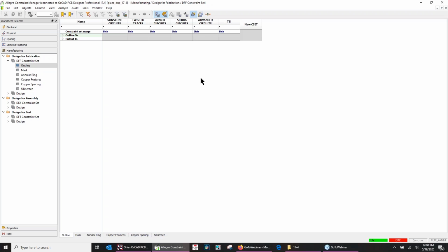What we want to do is say, why do that as a post-process? Definitely why do that after you've sent it to the board house and you're waiting to hear back from them. When you really think they're building your board, they're doing checks on it just to put it on hold and send it back to you to tell you there's problems. And trust me, if they overbook, they're going to find some reason to put your job on hold. So we want to bring those checks right up front, and that's what we're doing here.